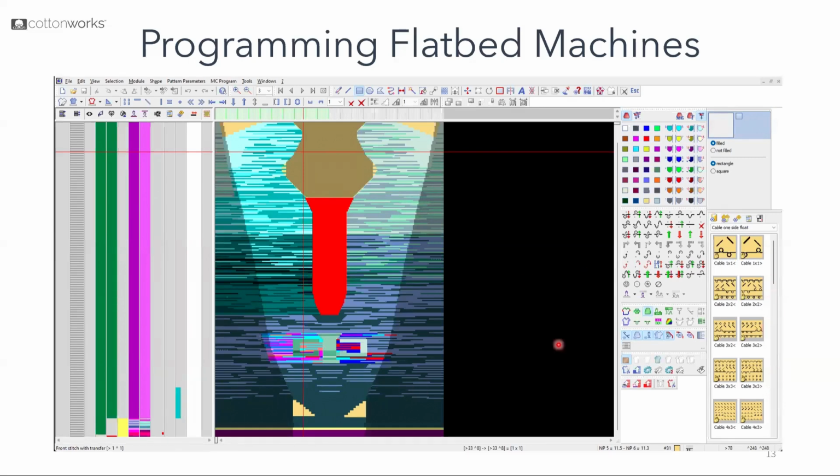Over here, we also have control columns. These ones control the takedown of the knitting coming off the machine. We can control the speed of the carriage. We can also control how much yarn goes into the stitch, so if we want a tight or a loose stitch. There are many other features that we can use on this program because this goes all the way to programming entire garments, but there's a few just to start off with.